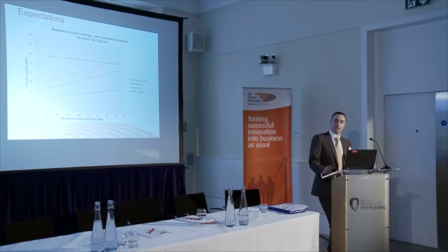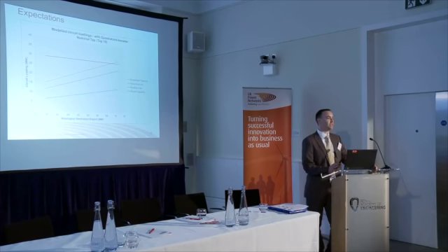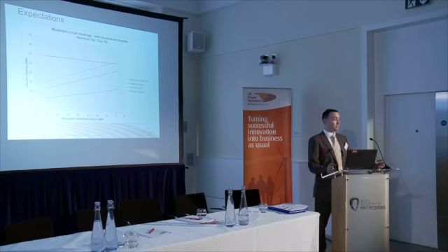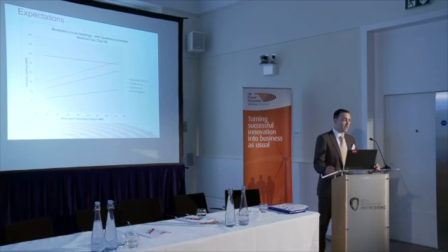If we move now to this, this is what we've modelled the quad booster's impact at nominal tap. When I talked through my example earlier, for most of you that were here, you may remember that I said the quad booster has no effect when it's on nominal tap. Obviously, that's in a perfect circuit, and the quad booster we have installed has an impedance, as you've heard. This impedance actually affects the power flows through the circuit. So this change in power flows isn't a result of the tap or change in phase angle, but as a result of the impedance of the quad booster.